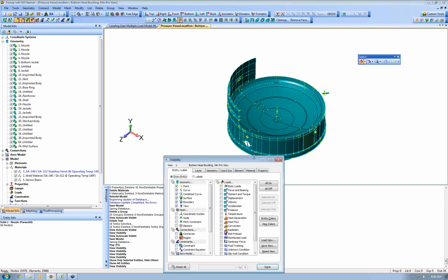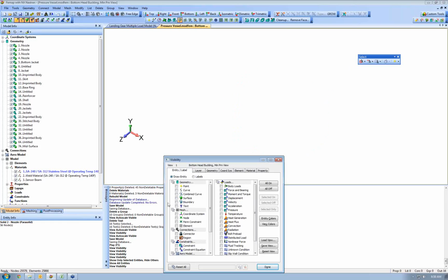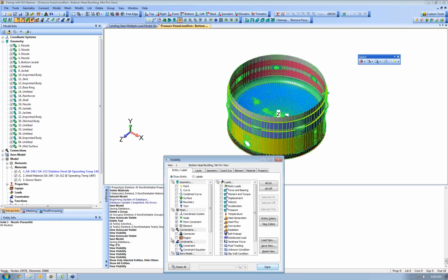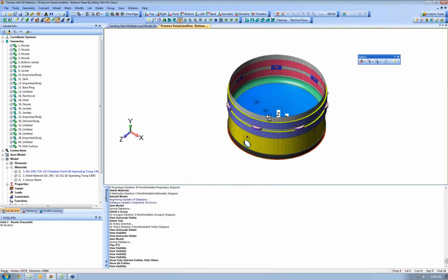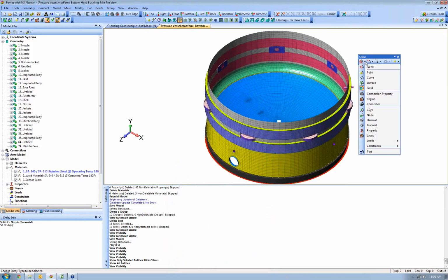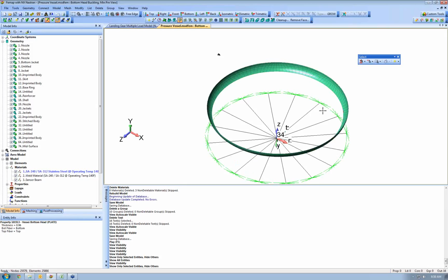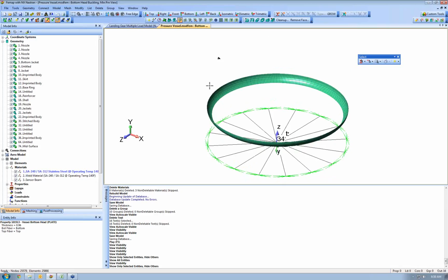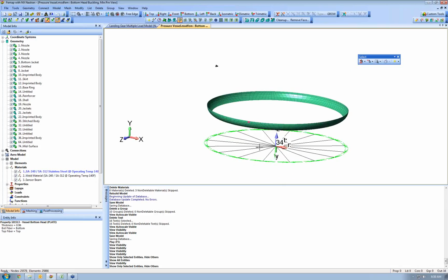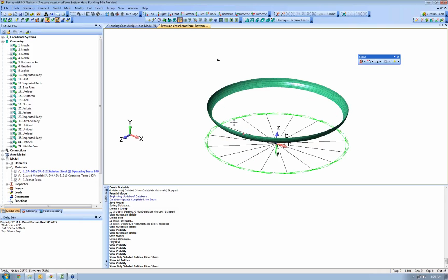So I'll go ahead and I'll switch gears. We'll play with the mesh. Now this time, rather than using solids, I'm going to use properties. And same trick, right click, visibility, show selected only. Now I've just got that one property that I selected. You'll also see some other elements in here. Those are rigid links, so they have no property.